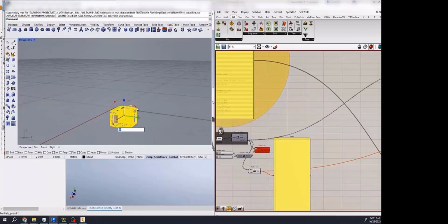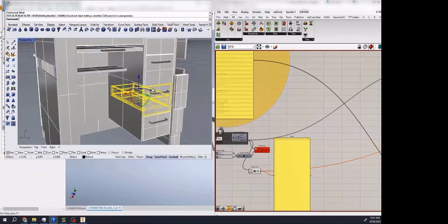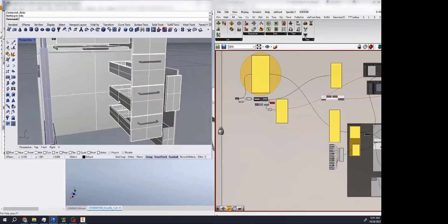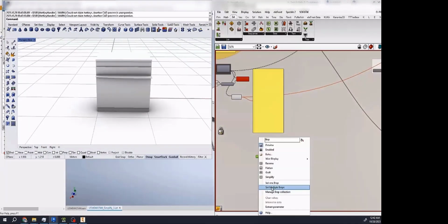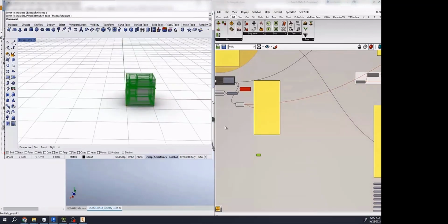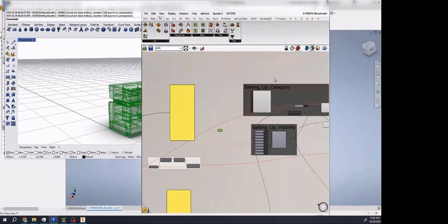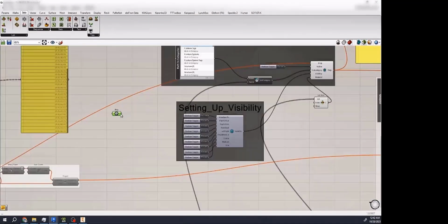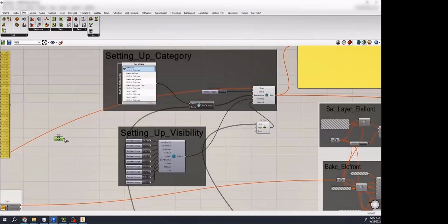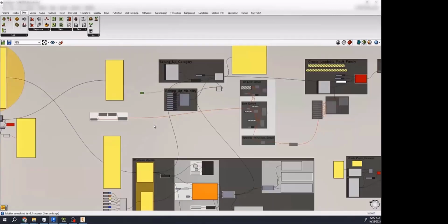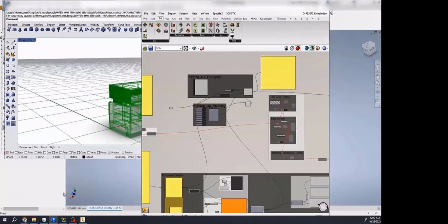You can bring them into Rhino, and in Rhino you can do a more precise model check. When you think it is perfect for a Revit native family, then again we do the same process. In this case, I'm referencing all the BREP geometry from Inventor and bringing it into Rhino inside Revit. Once you have this pipeline and a script is prepared, we can basically produce thousands of assets as native Revit families.